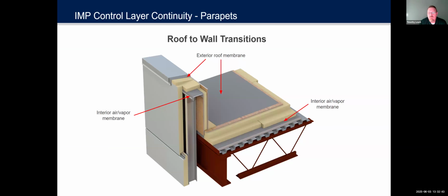Okay, so other considerations to remember is we're talking about walls, but you have a whole building here. You have roofs also that you're going to deal with, and whatever situation you have in your roof, in this case a roof membrane, that membrane needs to continue to the wall surface. Those two need to connect in order to work properly. You can't have a gap between the two of them. That should go without saying, but it needs to be said. Whatever surfaces you have for a roof versus your insulated panel, those need to mate together.